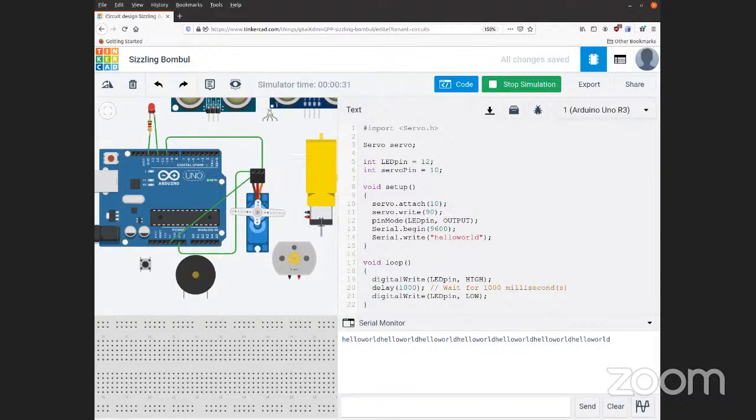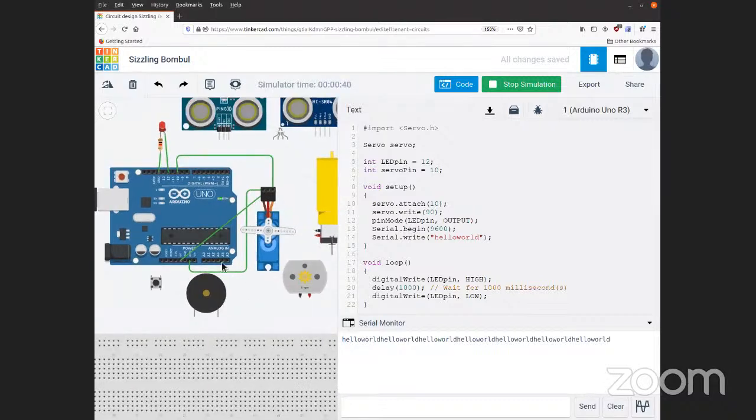Yeah, definitely the serial monitor will be your friend, because you will assume that you did something, and then that won't be the case. You can actually read back pins. You can set pins high and low, but you can also, so you've got the LED pin high and low, read them back to know what you set them to.